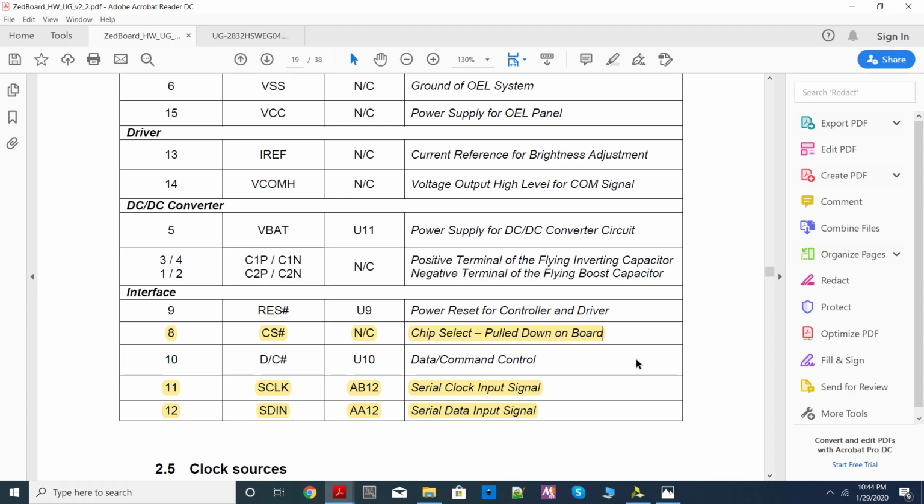The only thing I would like to add is that SPI is usually called a 4-wire communication protocol because there are 4 wires: 1 wire for clock, 1 wire for data from master to slave, which is called MOSI, master out slave in, 1 wire from slave to master, which is called MISO, master in slave out, and 1 wire called slave select, which is basically used for selecting a particular slave.